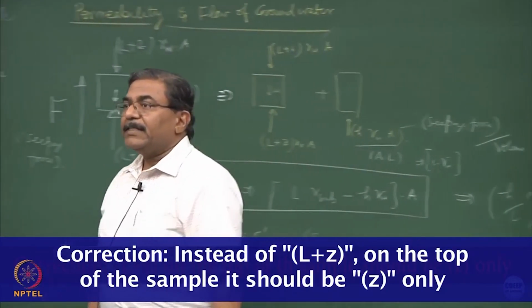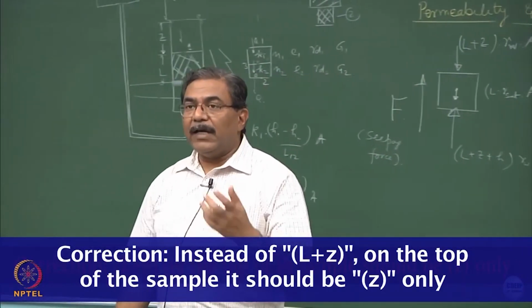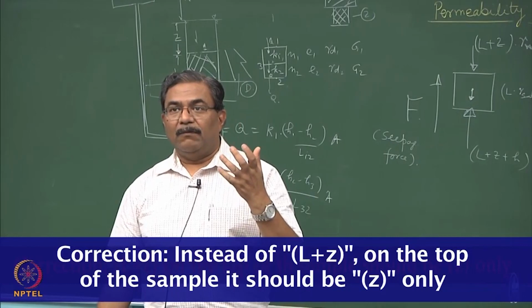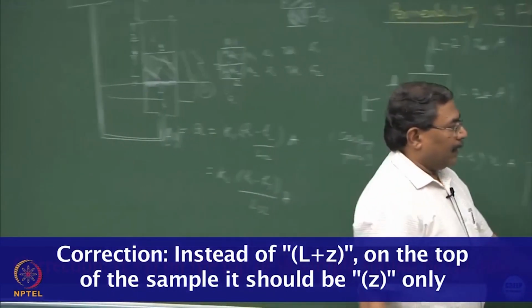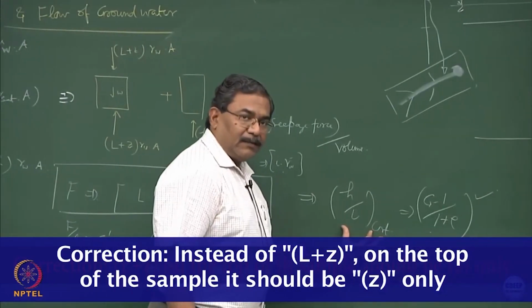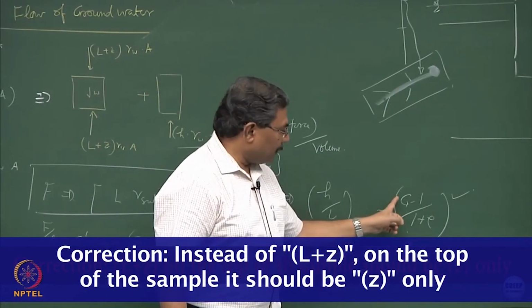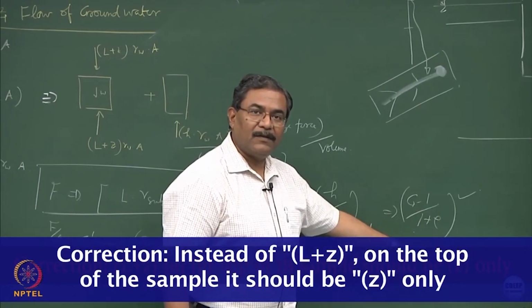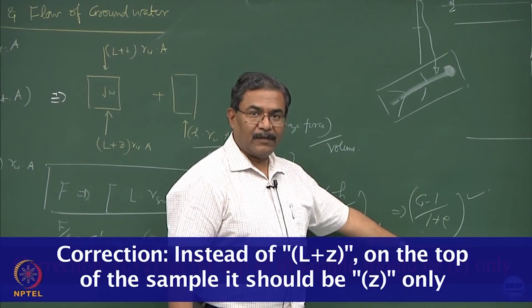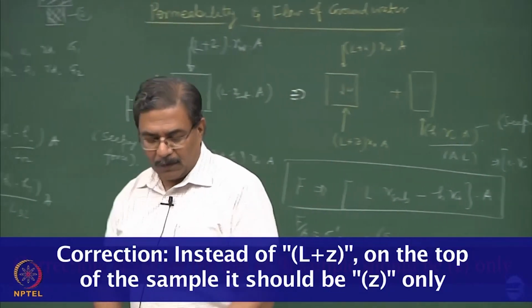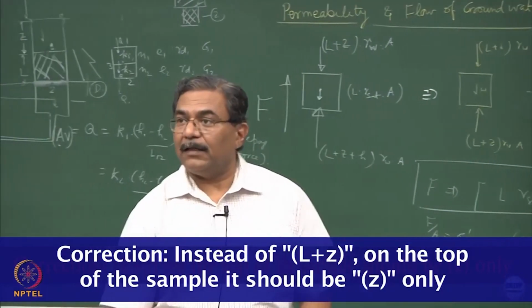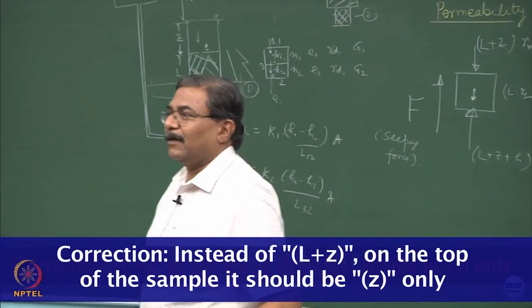What it indicates is, a soil is going to boil under hydraulic gradients, and at that time the hydraulic gradient is this, which is equal to the specific gravity minus 1 over 1 plus void ratio. Have you understood the whole story or not?